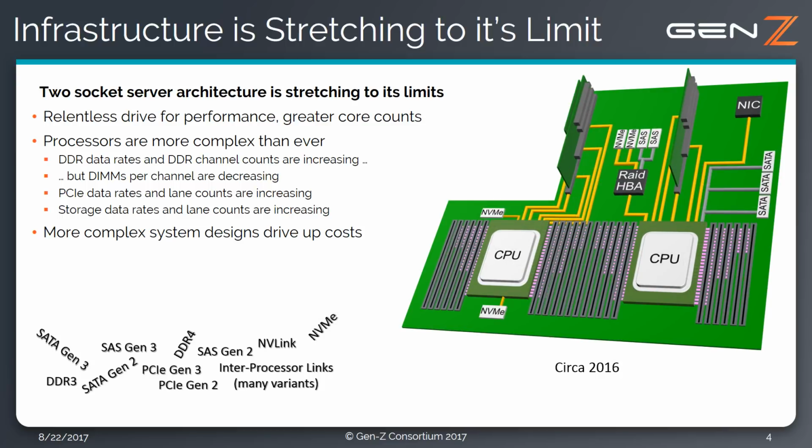Now, circa 2016, the CPUs expanded to 6 DDR memory channels per CPU socket and added additional PCI links, lanes, widths, and slot count. CPUs also integrated SATA links to support low-end storage requirements. DDR Gen 4 was now prevalent, and additional interconnects, such as GPU-specific NVLink technology, emerged.